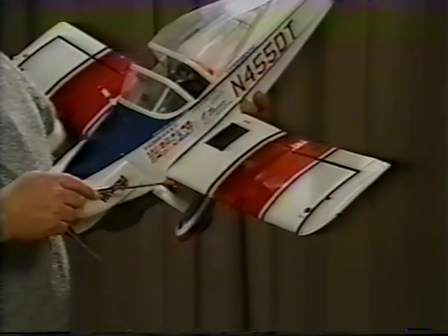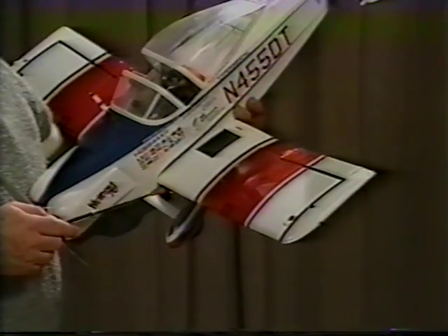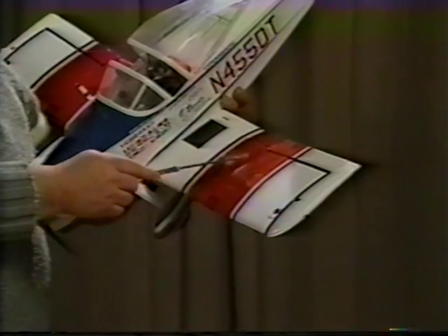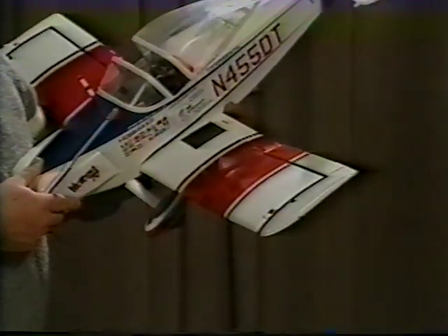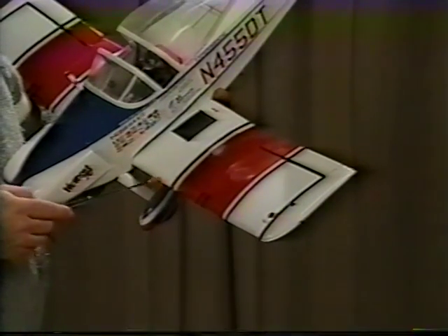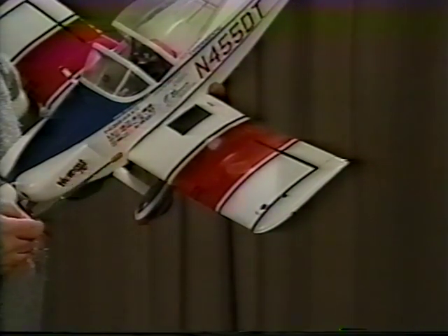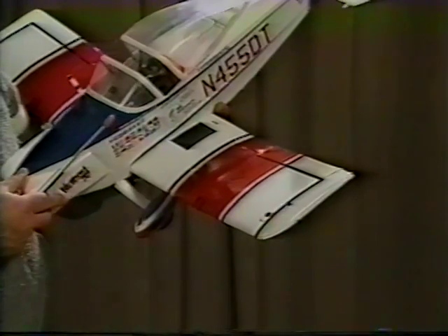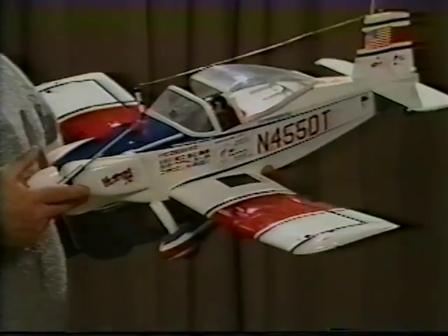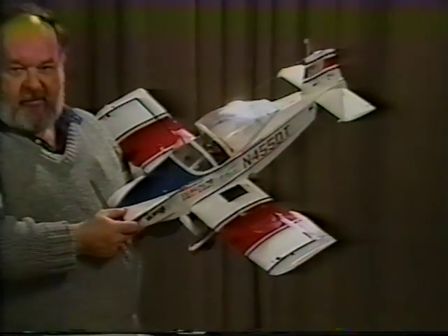You can, of course, put a stall strip on the leading edge inboard if you want to, but in this particular case, the stall pattern will probably generate about the middle of the wing. It isn't ideal from the standpoint of the stall pattern. You maybe would like it a little bit further inboard, but it's really not too bad either, because there still is a generous portion of the outboard wing that will be working. This sort of represents a normal design compromise.